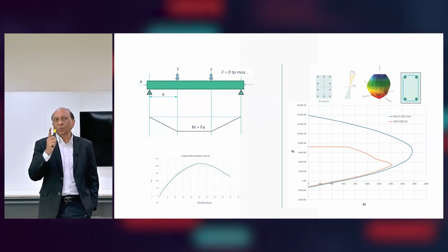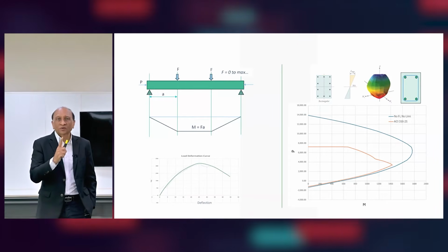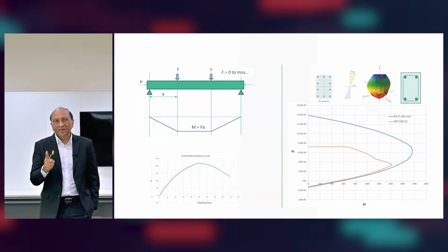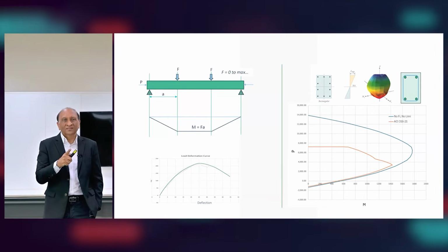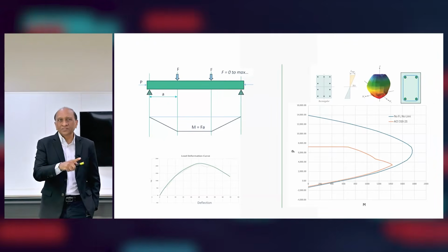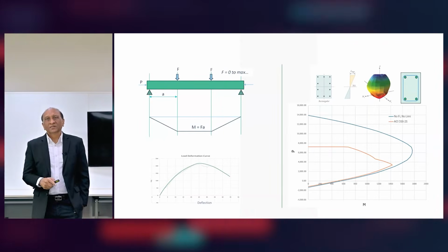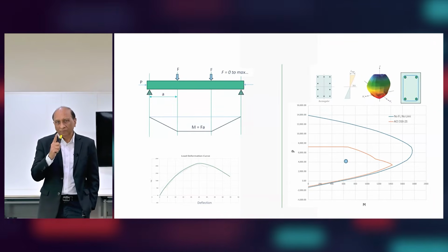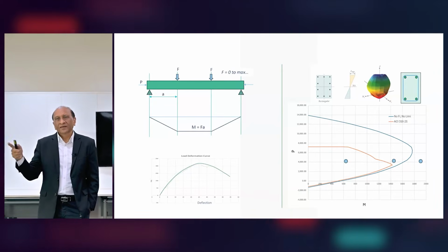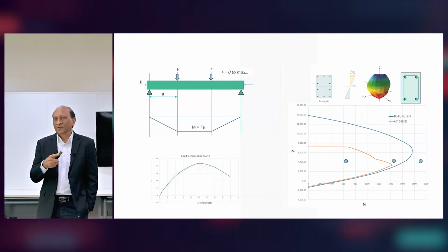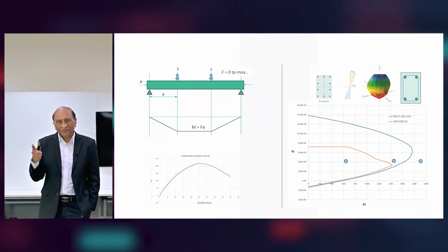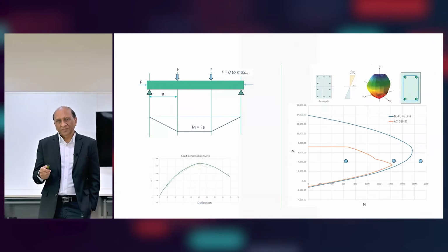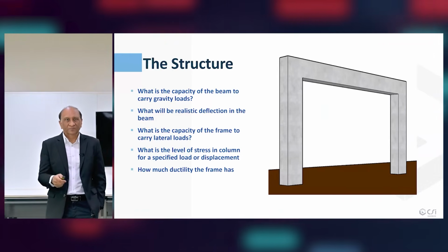So that means it's just one point on that curve, and that too not real because it is based on factored load and factored capacity, but the actual load applied here, F, is not factored. So we can't really get a correlation between real load and the capacity diagram that we have here. Theoretically it may be one point, but actually load can vary along this curve at any location. Moment can vary from 0 to any moment, and all of them will exist until the beam really breaks down, assuming that it doesn't fail in shear first.